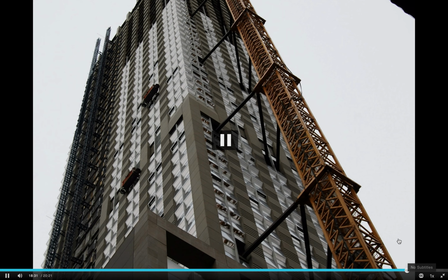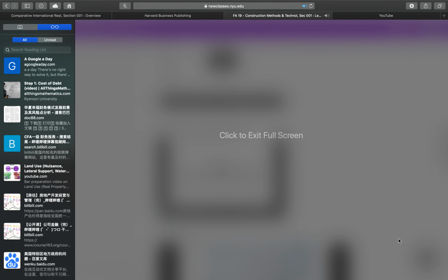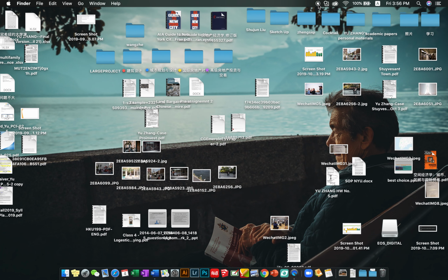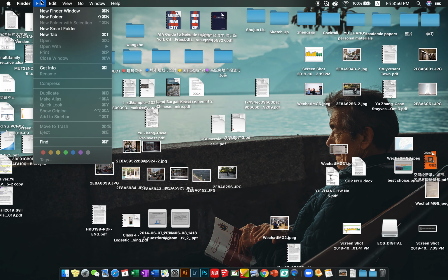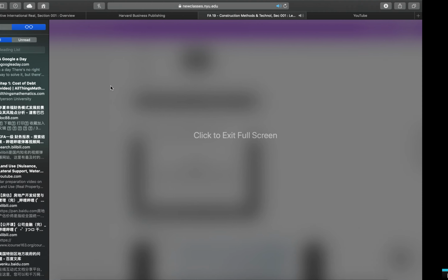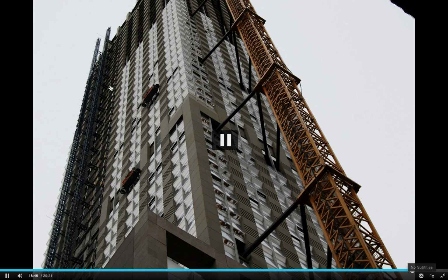Okay, so as these tower cranes get increasingly high, obviously you have to support the tower so that it doesn't fall, it doesn't tip, it's not affected by wind, it doesn't pull out. All right, so what you can see there is the bracing that gets installed into the building under construction. And that bracing connects directly to the structural frame. And that has to be planned when you're detailing your structural steel, so that you have those locations ready as you go further up your structure.